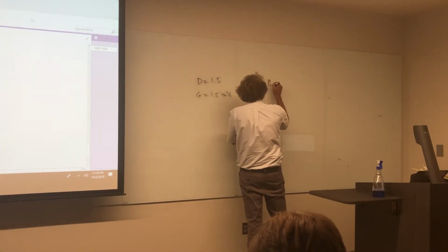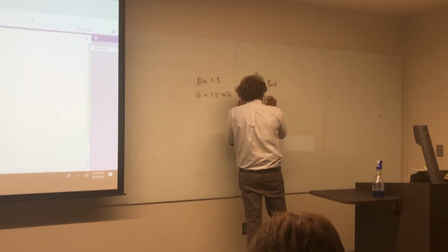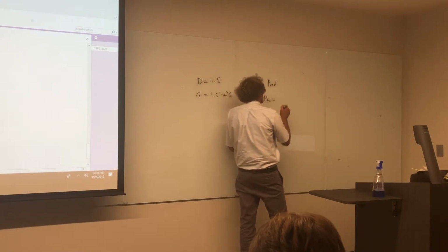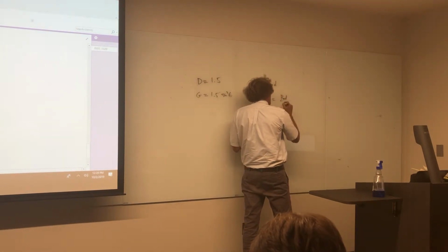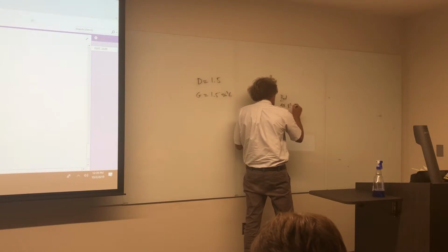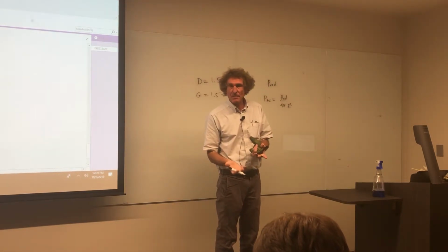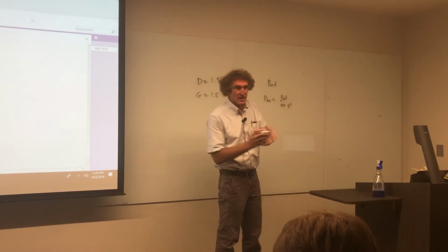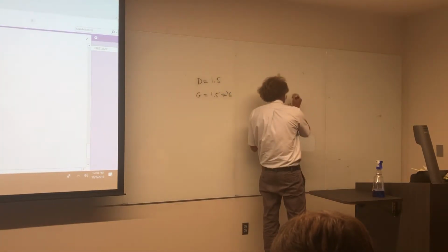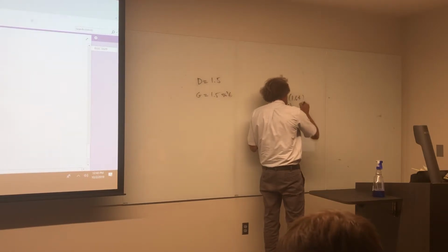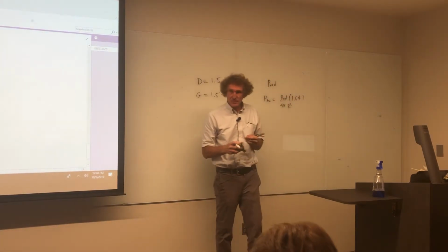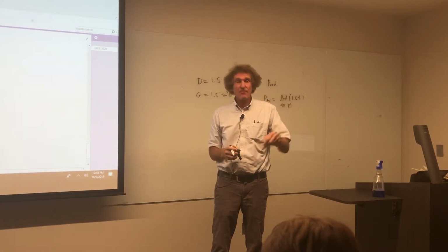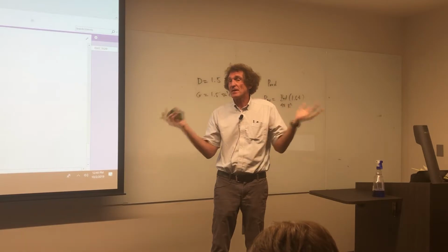Once I have P rad, the next thing I want is the average power density at a given point. And I can say that's equal to P rad, right? Divided by 4 pi r squared. That's as if it's an isotropic radiator, right? Times the gain of the antenna. That was a half-wave dipole. This is the one we did cover in class and mentioned several times. This has a max gain of 1.64, right? Y'all remember going through this? That was the dipole's 1.5. The half wave is 1.64, and then everything else you have to calculate.